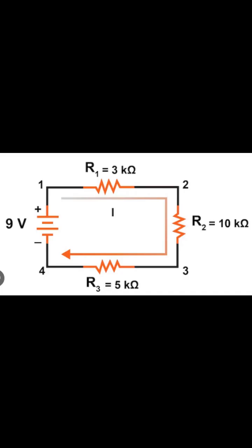6.1, Series Circuit Principles. The series circuit has only one path for electron flow through the devices wired in the circuit. There are three formulas used to explain the laws of series circuits, as seen in the picture, where N is the total number of voltage sources, resistances, or current sources in a circuit.